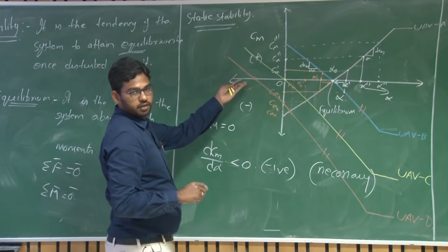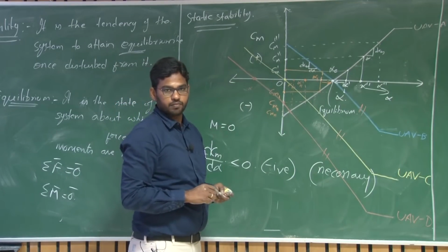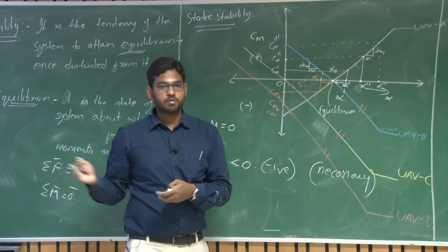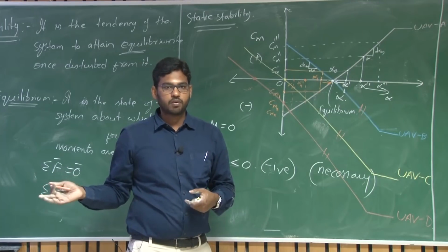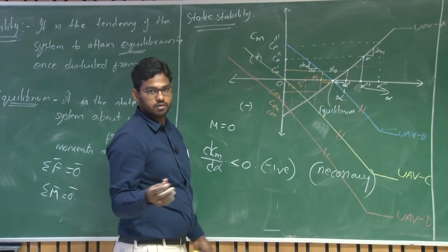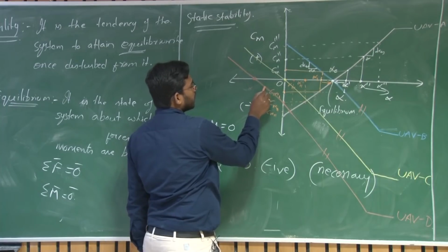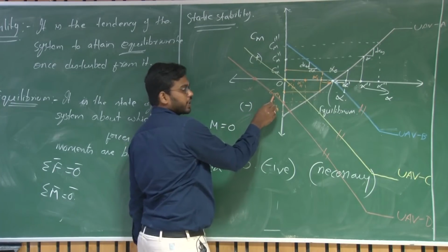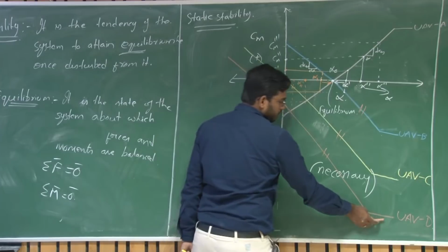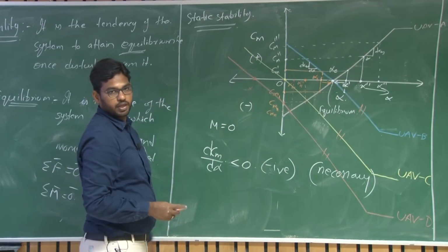So it is an inefficient flight, right. The whole idea is to generate lift at minimum velocity and minimum power requirement conditions, or minimum fuel consumption, right. So although you have Cm alpha negative even for this UAV D, you can't trim this at a positive angle of attack.